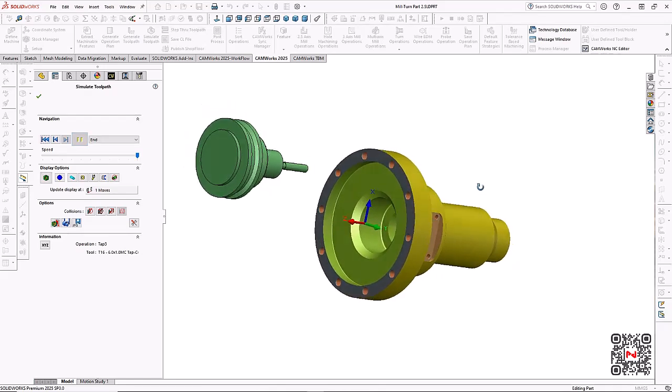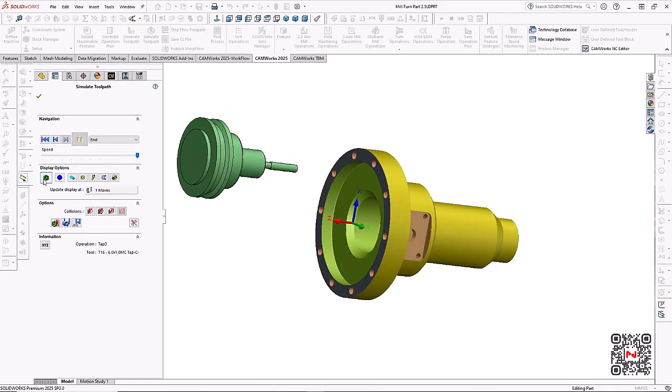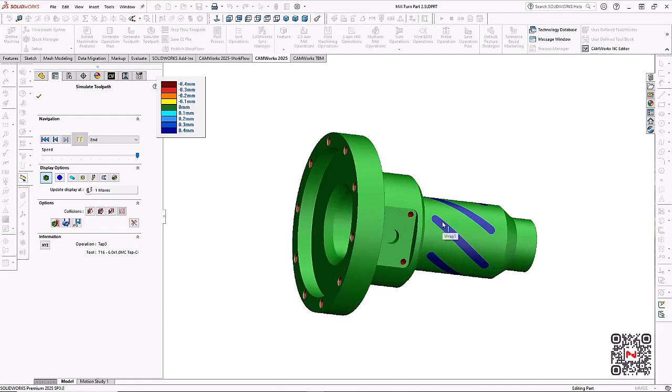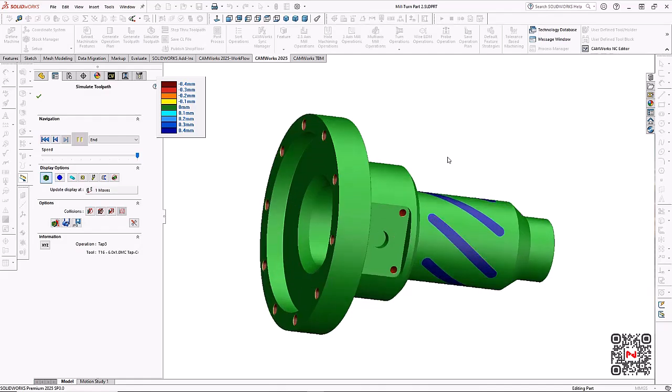You can see the machining, and I'll go ahead and compare the machined model to the design model, and you can see that everything in green is net to the design model. There's some blue here. We have not machined the wrapped features yet, and you'll also see some red there for the tapped holes, and that is because the holes are modeled as the tap drill size rather than the major diameter of the tap. So hence they are in red.